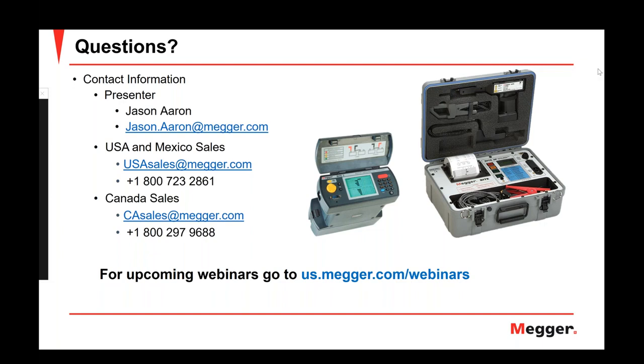So you want to set the voltage properly, and that's why, as part of the verification that you do every time you go to check the battery or do the inspections, you check the float voltages. As part of the results, the form shows you the total voltage, and you can compare that to what it should be. If it's not like that, then you should take action. There are many other things to consider, but temperature and float voltages are the ones that I would recommend initially to take care of.